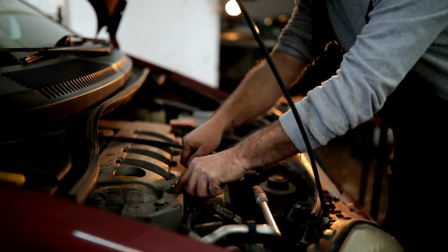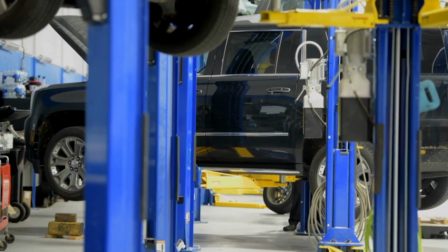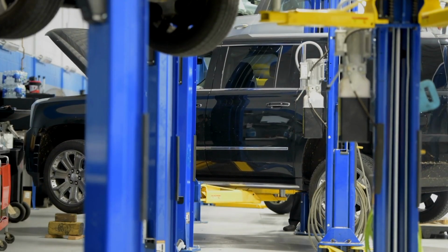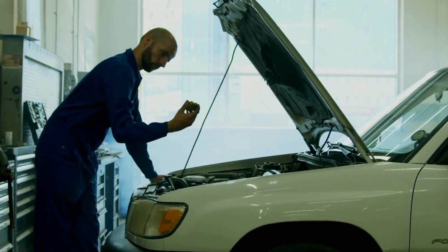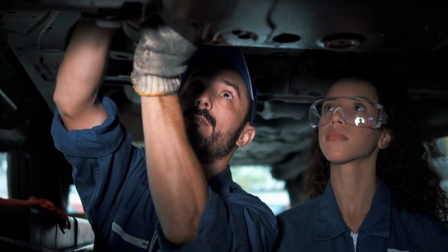What causes DTC code P0003? Faulty fuel pressure actuator, short or disconnection in the actuator circuit, leaks in the fuel system, fuel pump problems, faulty fuel pressure sensor, engine control module, ECM, malfunction.